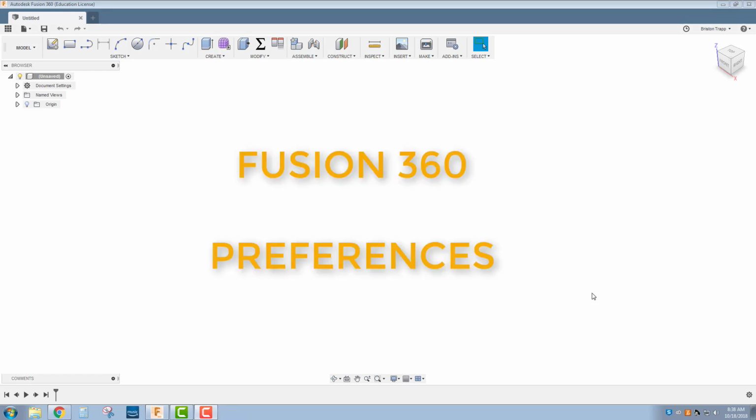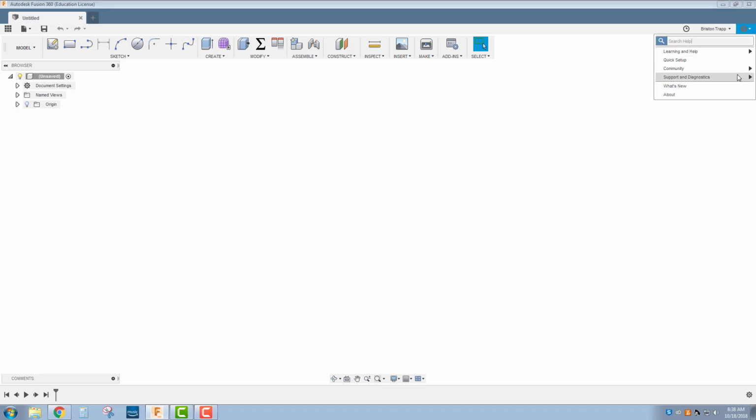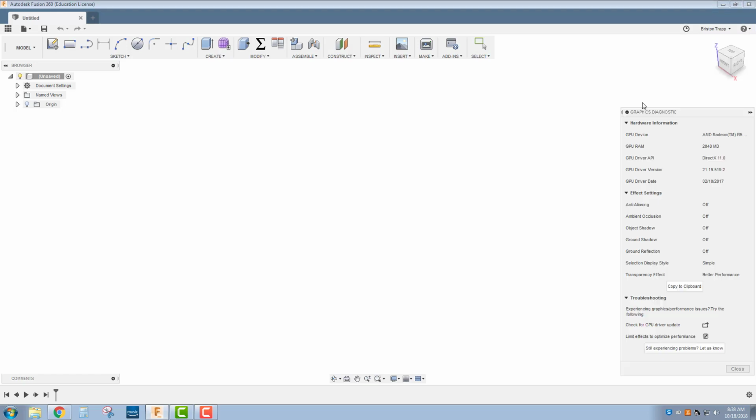This video will show you how to set up your preferences to use Fusion 360 in class. In the upper right hand corner, there's a little question mark for the help menu. Go to Support and Diagnostics and go to Graphics Diagnostics. What we need to do is to limit effects to optimize performance. So check this little box and that will help with a little bit of the glitching on some of these slow computers.